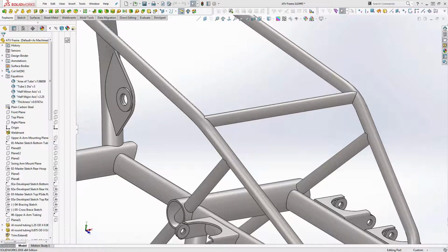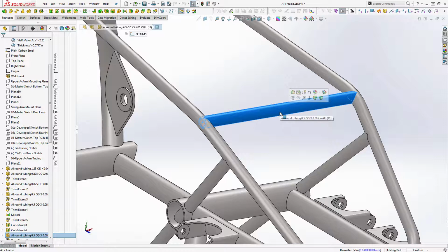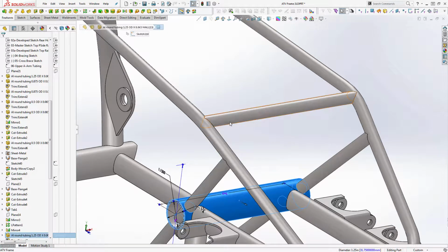So as you can see in the picture here, we've got this cross tube that we're going to be working with. A lot of times when you're frame building, you'll find that you've got a bigger tube that needs to come into two smaller tubes or one smaller tube. At least in the BMX industry, the common thing to do is to crush the end of the tube or ovalize it, so that it fits across the entire tube without sticking past. There's different styles, right? One style being this open tube down here, and then this style being mitered ends.